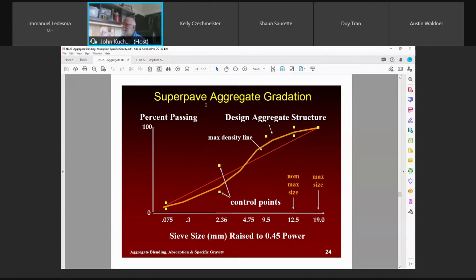But what's the reason for their change? Superpave takes into account your performance graded asphalt cements. Remember, we looked at it a little bit briefly where it looks into existing asphalt cements during the service life, whereas Marshall only tests in the barrel, if you want to call it, or in the tank asphalt cement when you're just adding it to the mix.